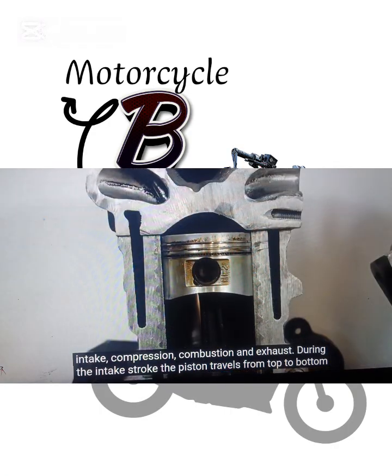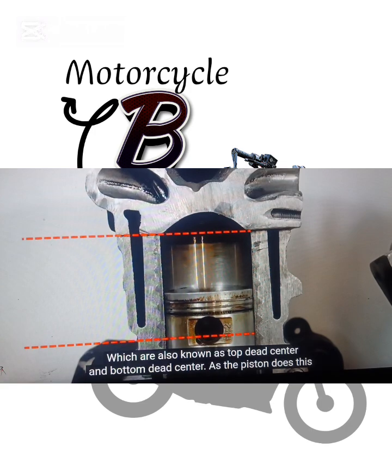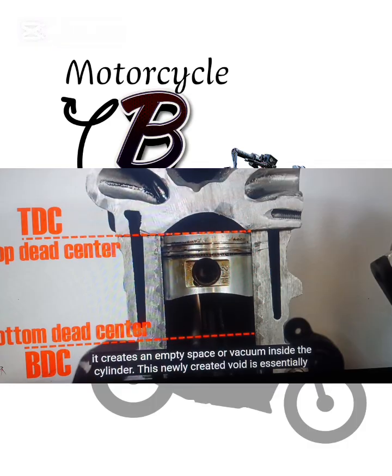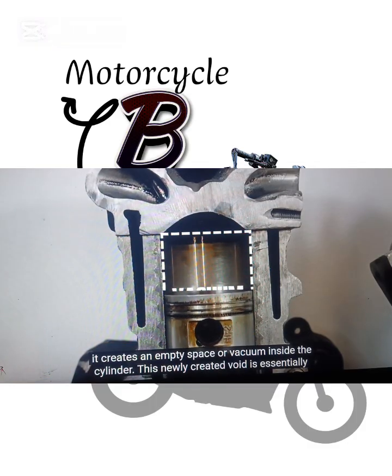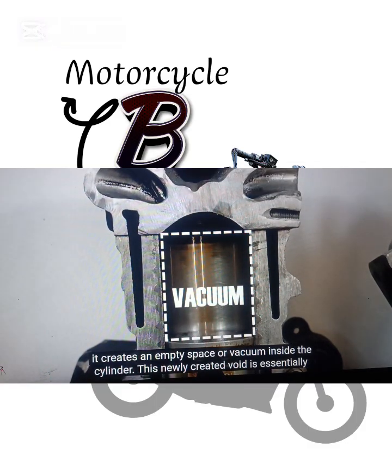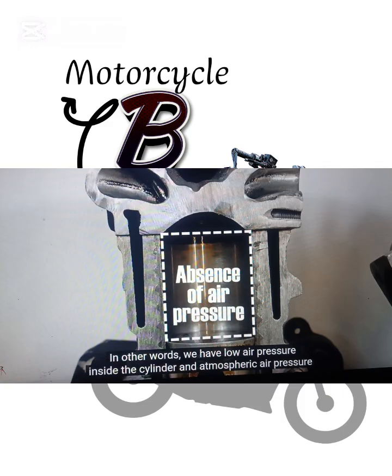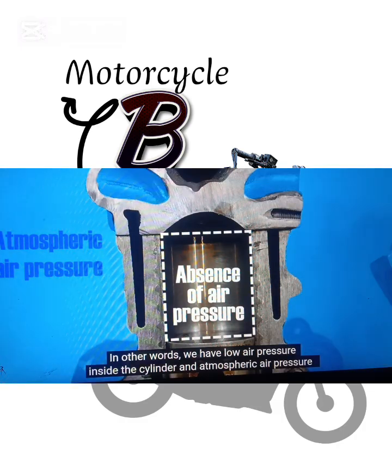During the intake stroke, the piston travels from top to bottom, which are also known as top dead center and bottom dead center. As the piston does this, it creates an empty space or vacuum inside the cylinder. This newly created void is essentially a brief absence of air. And because we have an absence of air, we also have an absence of air pressure. In other words, we have a low air pressure inside the cylinder and atmospheric air pressure outside the cylinder. This air pressure difference cannot continue to exist, and air naturally seeks to equalize pressure everywhere.